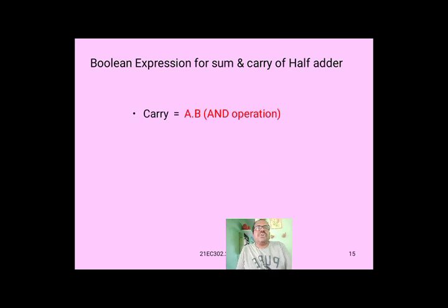Boolean expression for sum and carry of half adder. Carry means AND gate, that is A into B. Sum means XOR gate, that is A XOR B, that equals A into B bar plus A bar into B.